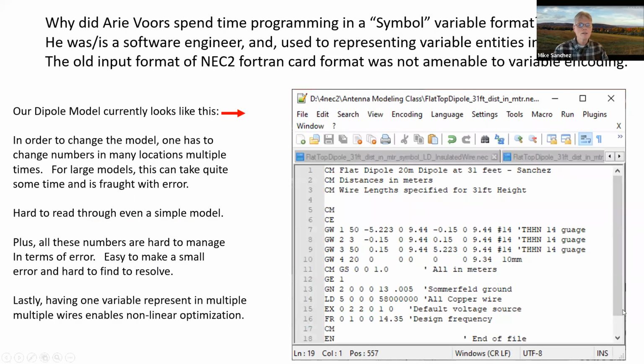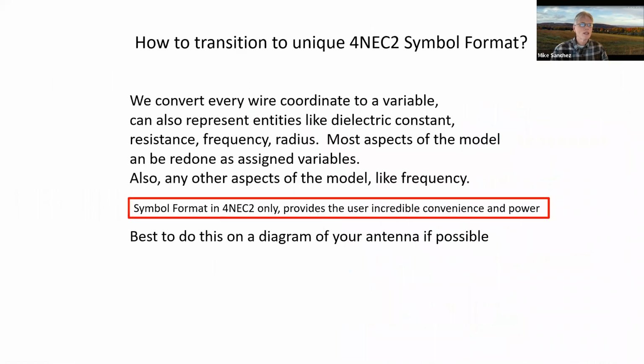If I have this model, the way I would find the new length is I would come in here, without knowing what to do, and just type in a number here, type in another number over here, and run the model over and over until finally, after 20 iterations or whatever, I come up with 14.0 megahertz, much as you would actually trim a real, honest-to-God dipole over and over. And unfortunately here, if I overshoot, I don't have to go get another wire and start all over.